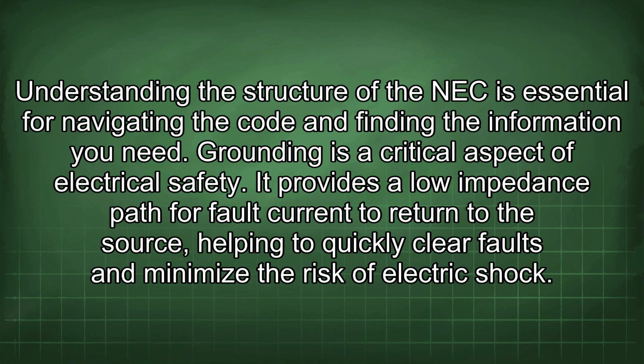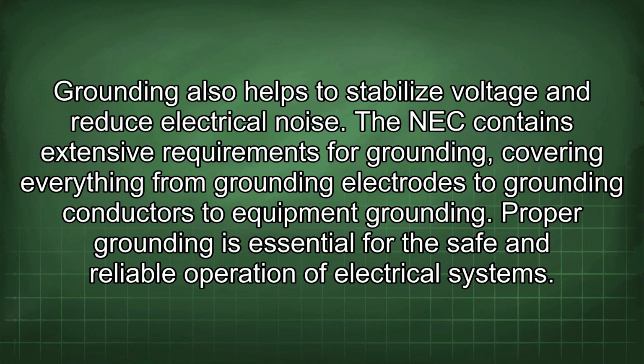Grounding is a critical aspect of electrical safety. It provides a low impedance path for fault current to return to the source, helping to quickly clear faults and minimize the risk of electric shock. Grounding also helps to stabilize voltage and reduce electrical noise. The NEC contains extensive requirements for grounding, covering everything from grounding electrodes to grounding conductors to equipment grounding. Proper grounding is essential for the safe and reliable operation of electrical systems.